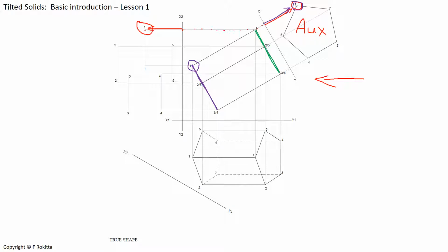Follow the track or the path, whichever you want to call it. From the x2, y2, we will place our divider at the intersection of our x2, y2 with the path, and we will carry over the distance of number 1 from the x2, y2 to number 1, plot the dot, and immediately again label the dot.